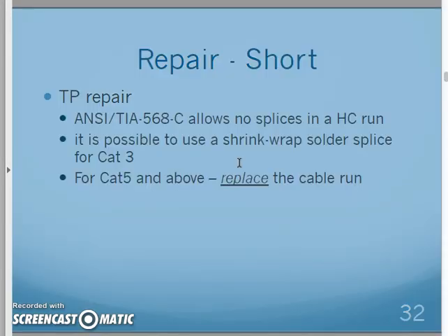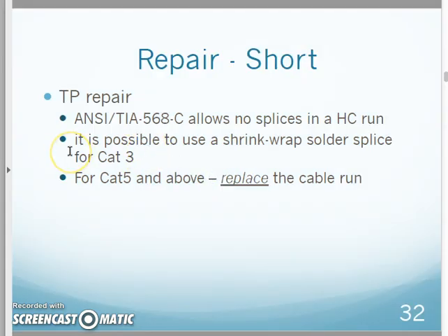Now, actually, let me finish that right here. That's what my standard is going to call for. If it's at the end, I can re-terminate. If it's in the middle somewhere, I'm going to need to replace the cable run. Okay. Again, I'll say it. If it's at the end, one of my bad terminations, re-terminate the end. Awesome. If it's in the middle of the cable run, I'm going to need to replace.